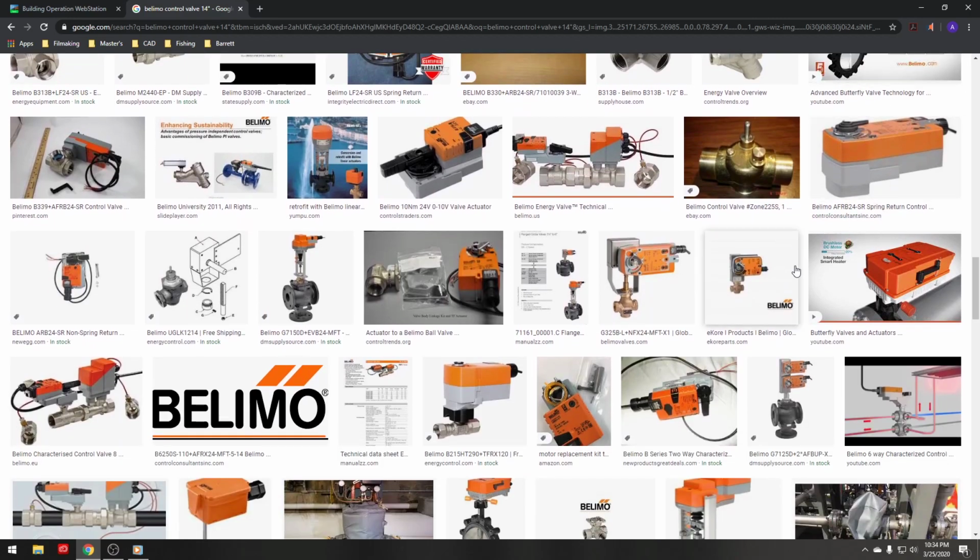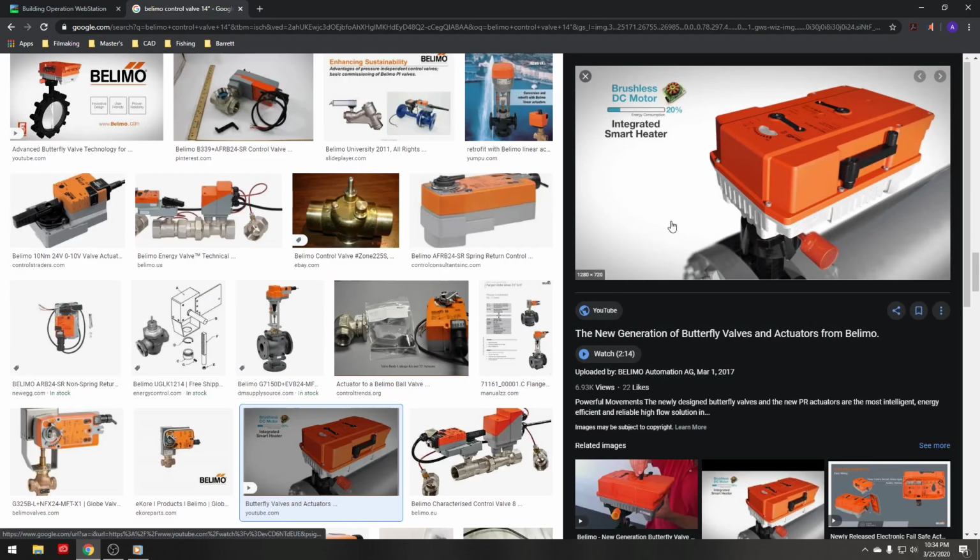So if you go up onto the roof and look at the chillers, there's this box on the return side of the chiller, and that's what we're calling a control valve. So these indicators indicate the position of the butterfly valve. So in this position, if it's 90 degrees perpendicular to the pipe, that means it's closed, and it'll actually say 0 degrees here, or 0%.